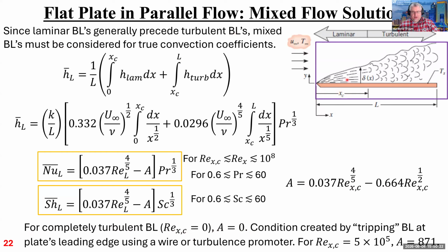Well, normally they do, but because the heat transfer is better for turbulent flow than it is for laminar flow, it is often the case that engineers will intentionally trip the flow to turbulence at the leading edge using a turbulence wire or some other turbulence promoter. Something that trips up the flow and gets it rotating. And by the time it gets down here, it's got some turbulence in it, and it transitions anyway to turbulent flow. And so flow is turbulent all the way down the plate.